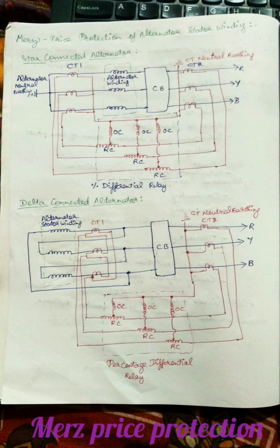Whenever the restraining coil is above the operating coil level, in the sense of the set value, there is no fault current and it flows as normal. When the operating coil overcomes the restraining coil, automatically a fault is sensed by this relay, and due to this it will initiate a trip to your circuit breaker and the circuit breaker gets opened.